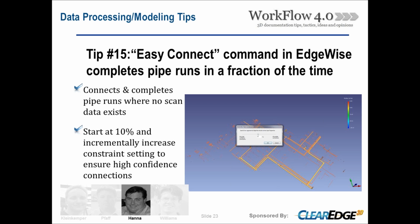So leading to tip 15, if you're running tools like Edgewise, there's some very powerful tools within the software. One of them is called Easy Connect. There are shadows inherent in scan data as you're picking up and scanning pipes. There's a nice feature in there that will connect and complete the pipe runs where no scan data exists. We've discovered through using the tool that it's better